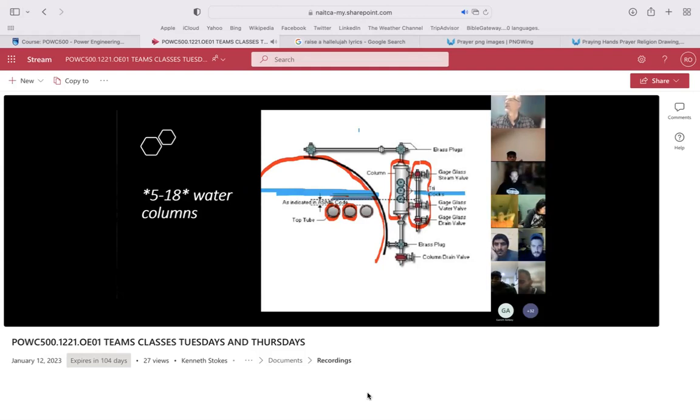Okay. So he showed some optional isolation valves here and here. This one does not have them. If the column does have isolation valves, they need to be locked open. Last thing you want to do is think you have a level in your boiler. A level is really down here somewhere, but you've got valves left shut and water trapped in this device.